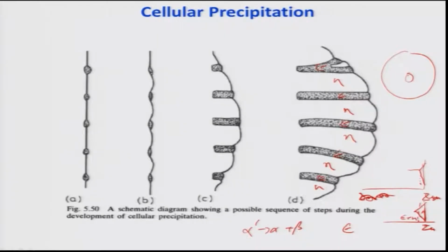The atoms diffuse from the bulk of the grain to the precipitate's boundary, and then the precipitate grows, as we have seen. Here that does not happen, basically because the diffusion distance is small; it forms a lamellar morphology just like pearlite, the diffusion distance is small, and it happens along the grain boundaries. So the lamellar morphology actually helps in reducing this diffusion barrier.